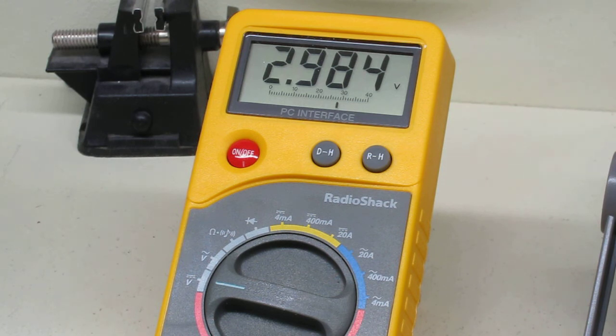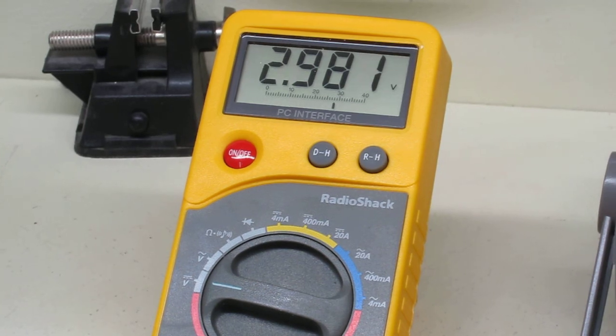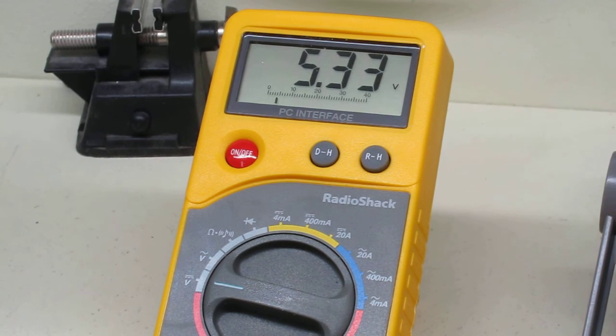Now, at a current of approximately 10 milliamps, the voltage across our LED is 2.983 volts. This is a fairly high voltage, and it corresponds roughly to the number of electron volts of the actual photon being emitted. Of course, we have some compensating to do for the electrical resistance of the device, which will be done during the analysis.